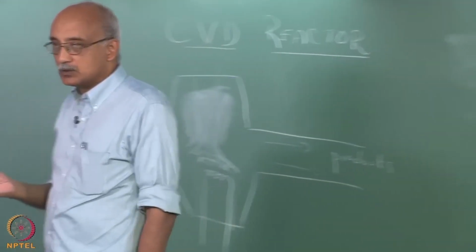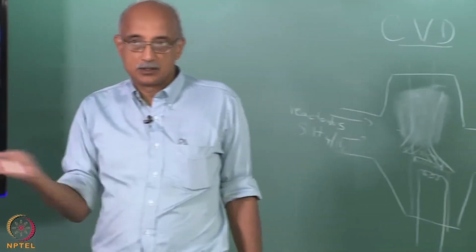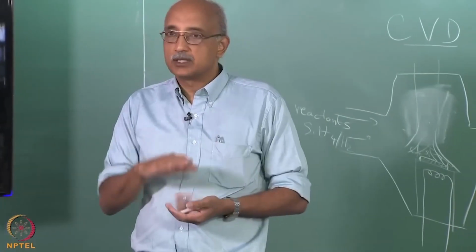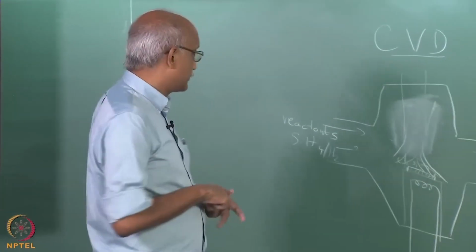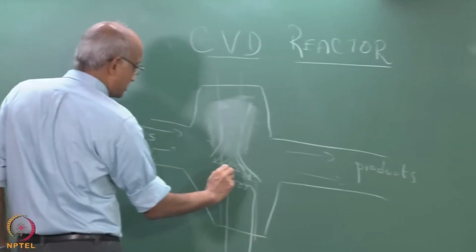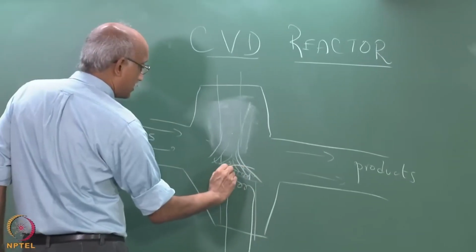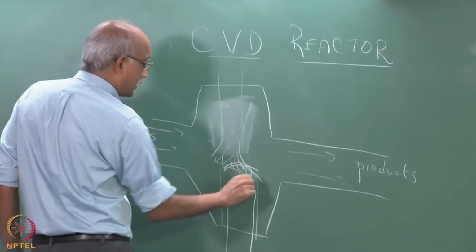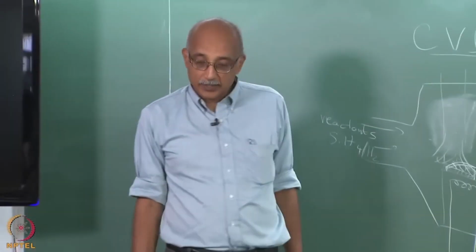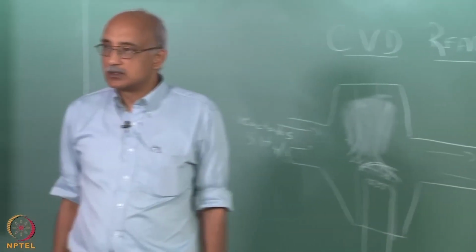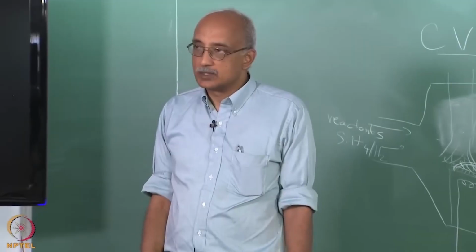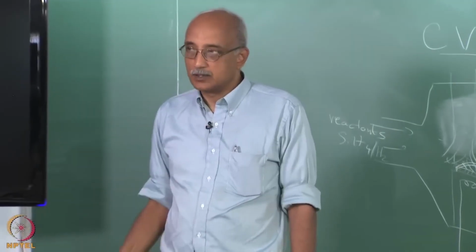However, as you know, when flow happens past a plate, you develop a boundary layer, right. So, if the flow is happening in this direction, you will essentially form a boundary layer that looks like that, and convective flow will essentially stop when it encounters the boundary layer. The velocities will rapidly decrease.